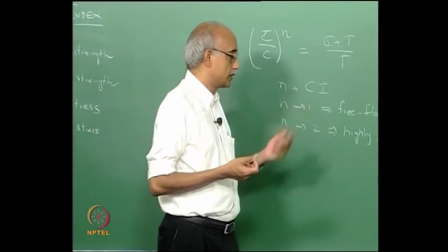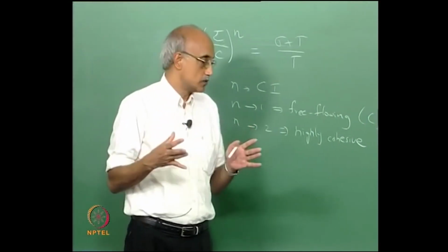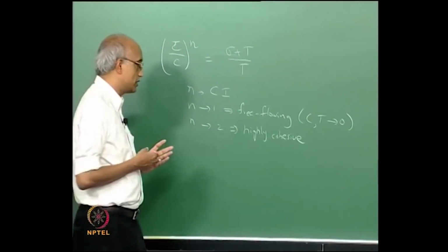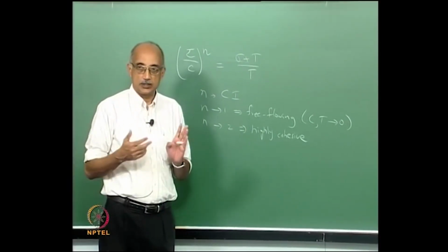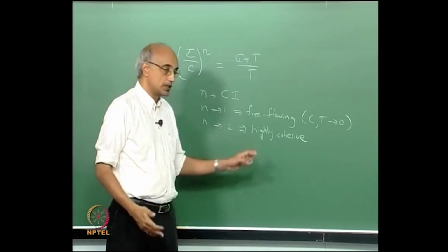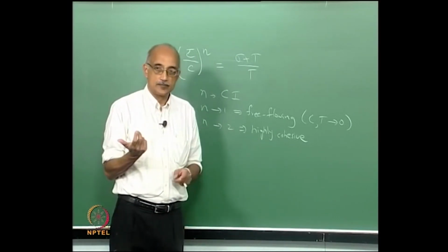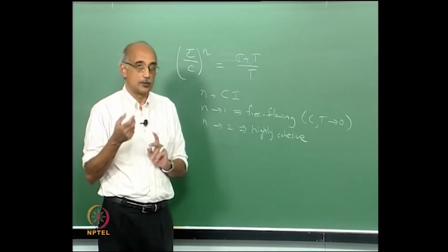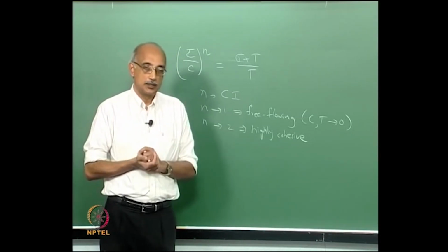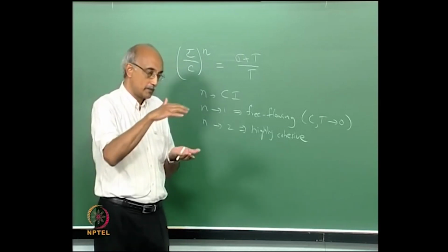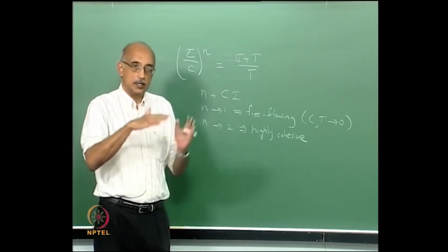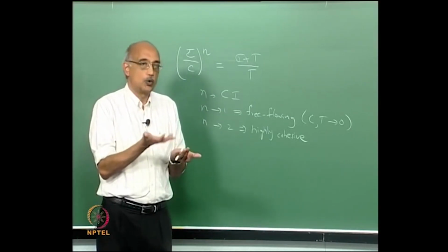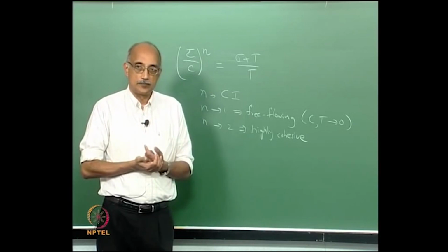So if you have a grain storage where you are in the free flowing regime, then the material tends to discharge in a fashion that is very different, because the cohesiveness affects things like the repose angle of the material that's stored. I'm sure you recall repose angle as one of the parameters that really dictates how material is stored in a silo, based on the angles that the material makes with the floor of the silo as well as the walls of the silo.